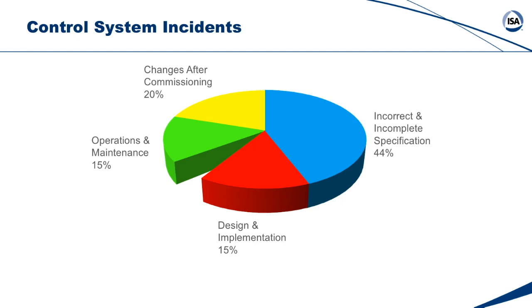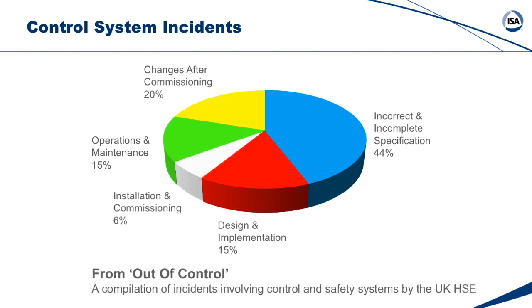So the sensor is now blind to the process. Not good. And even changes during installation and commissioning, where things were not installed per the manufacturer's recommendations. I know one end user reported in a study that 80% of instrumentation failures were traced back to the root cause, which was not installed per manufacturer's recommendations.